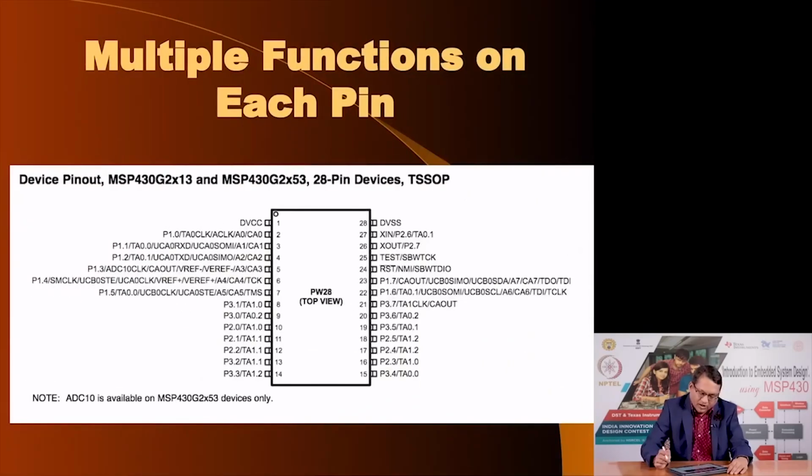It turns out that on our MSP 430 there are no separate power supply pins for the analog and digital parts of the circuit, even though MSP 430 is also a mixed signal type of circuit. It has ADCs, but they have not deemed it necessary to separate the power supply pins.